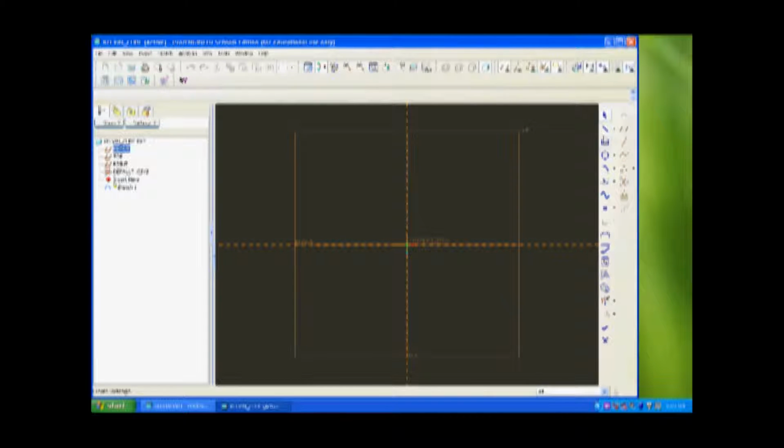Now, we just select the proper tool for the shapes or sketches that we want to create using the various tools in the sketcher. Since I'm making a cube, I'll choose a rectangle and then draw the rectangle.